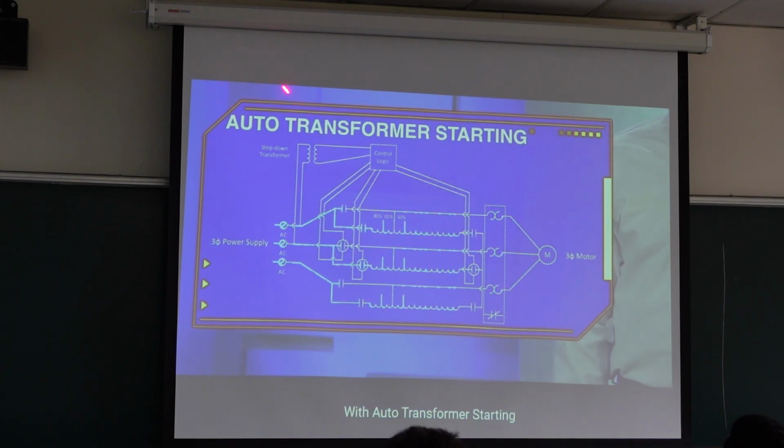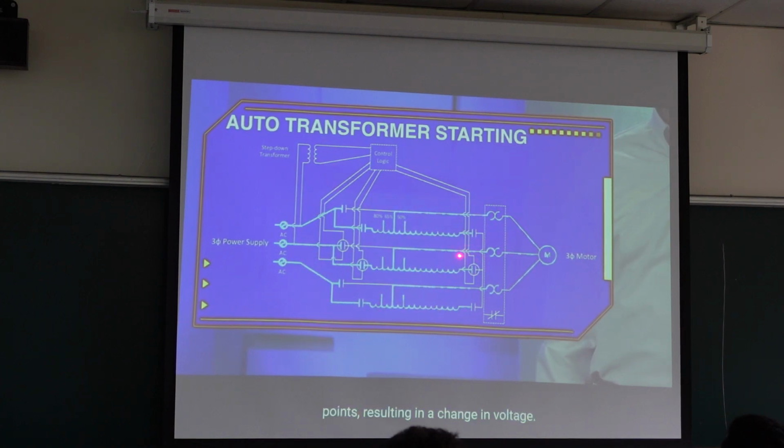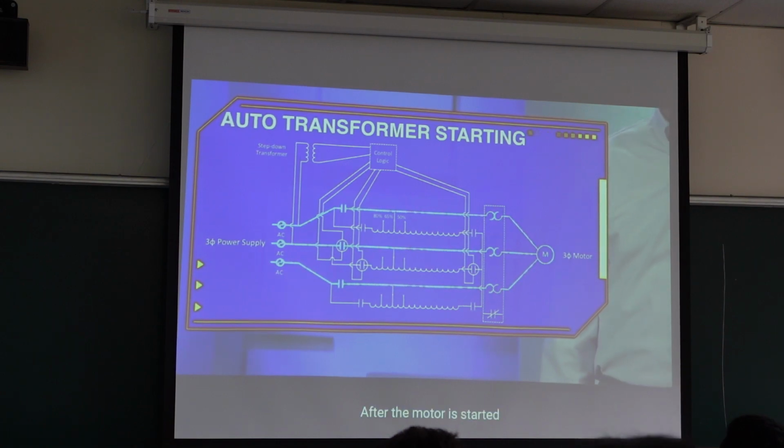And with auto transformer starting, we use auto transformer starting. We can change the voltage at different points of the transformer. After the motor is started, the transformer is bypassed.